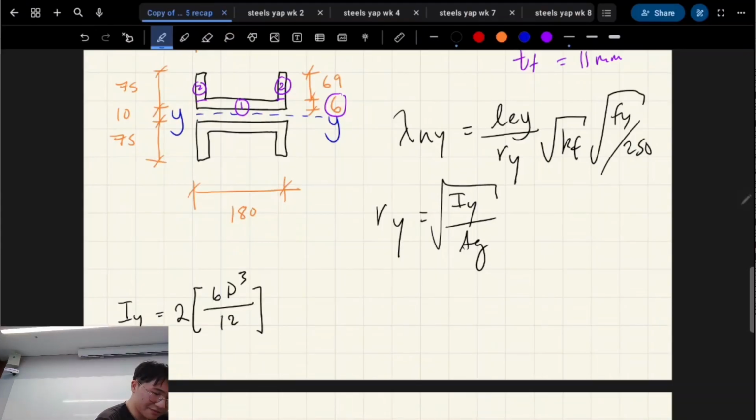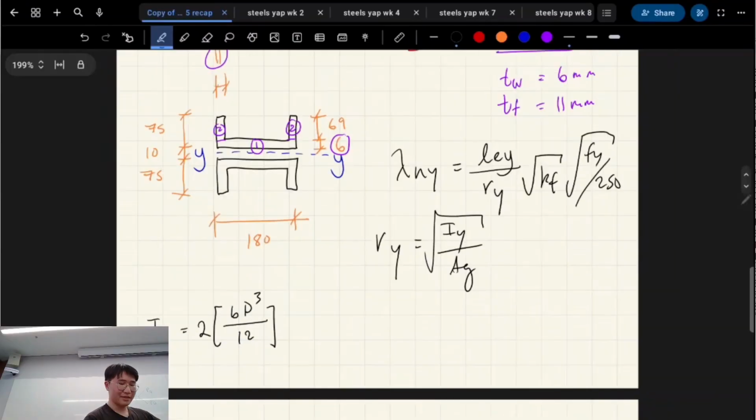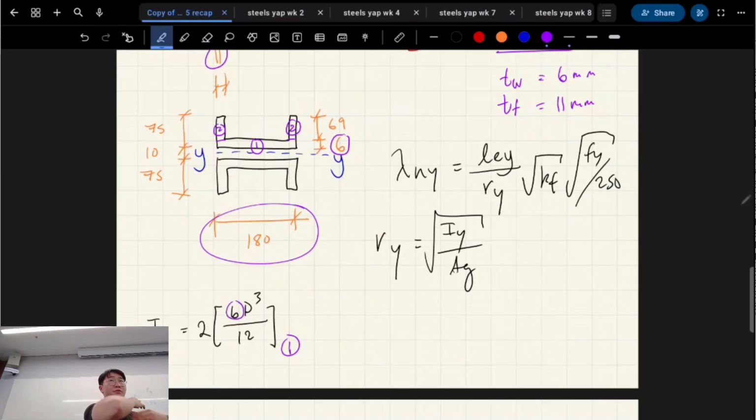Here's the moment of inertia for a rectangle, right? We're doing this for shape 1. Okay, alarm bells, right? BD cubed on 12. That shouldn't be for IY, correct? Not necessarily, because we've orientated everything 90 degrees, so the y-axis cuts through horizontally. When I say B, I'm referring to the left-right dimension. When I say D, I'm referring to the up-down dimension. So this should still check out. We're still taking everything relative to the minor axis, okay?